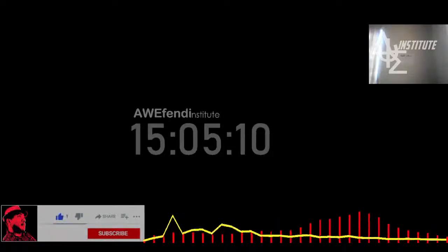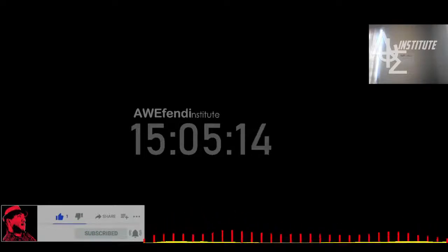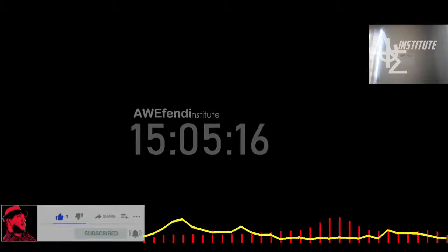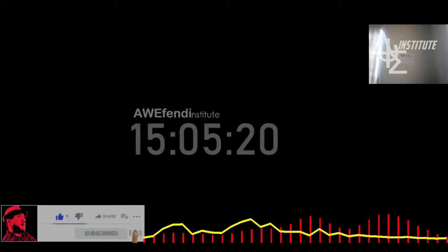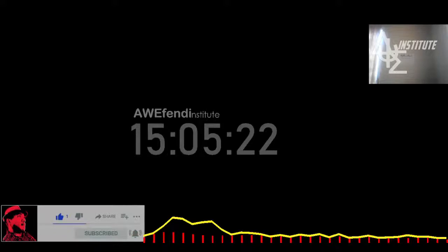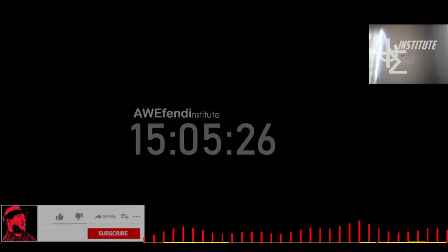So again, I'm going to go to our halo, which brings up our head-up display, and set up our fluid flow boundary condition. I think on one side it was 0.1 meter per second, on the top 2, and then on the right-hand side, we have an outlet with 0 Pascal relative pressure.